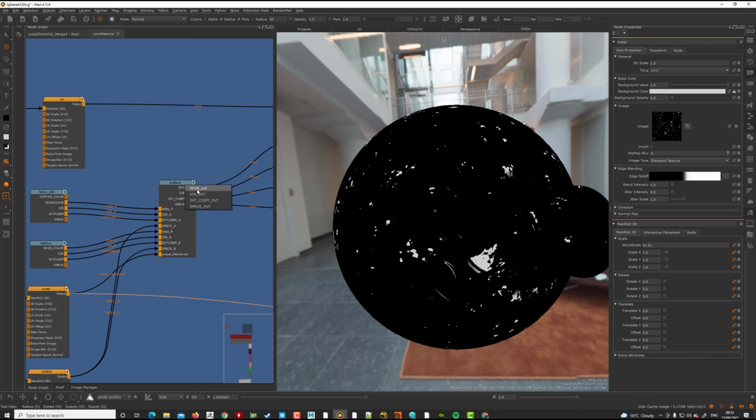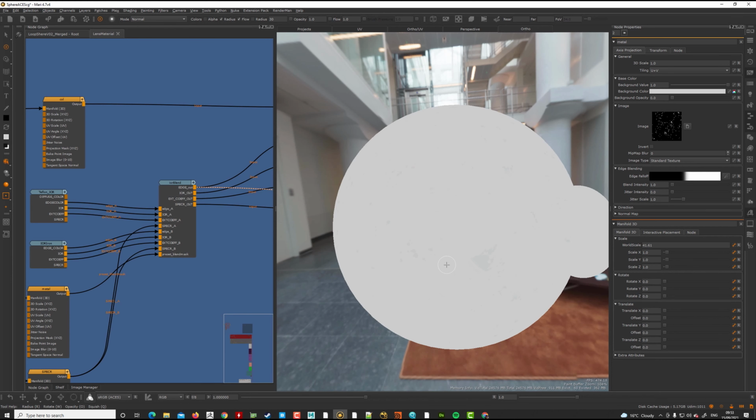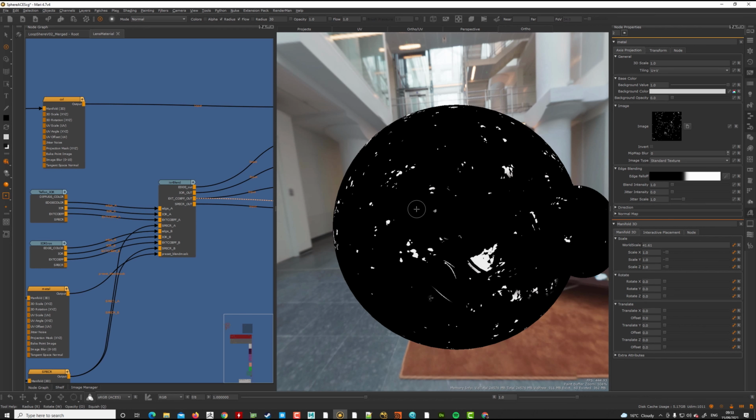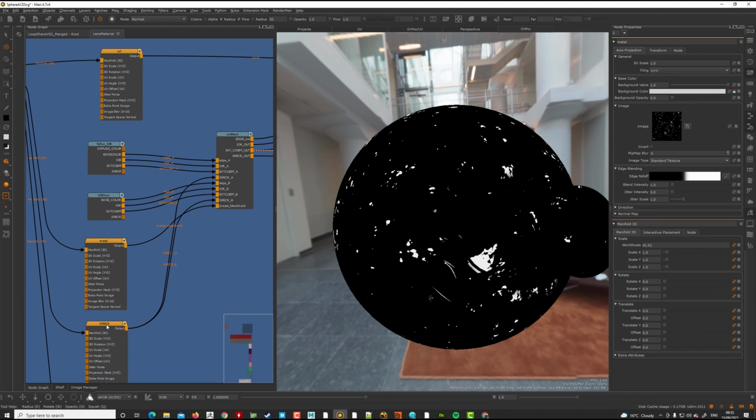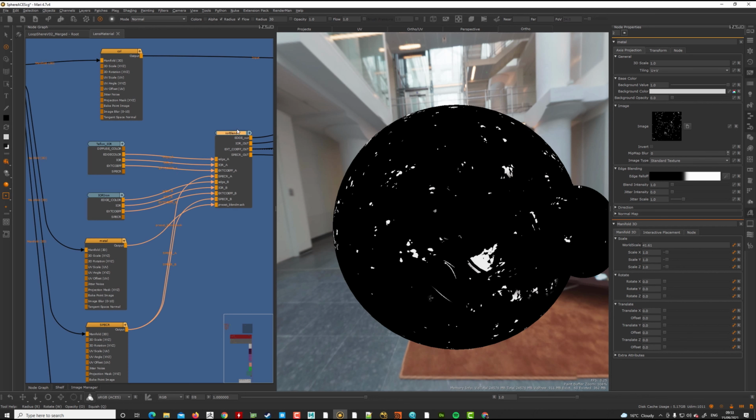Let's take a look at the maps here. Edge color out is going to be looking kind of whitish. IR is going to be the index of refraction values for these two materials, so these are float values. Some of the values here are far beyond one. Extinction coefficient is where, for example, it's non-metallic, it's going to be black, and you can see this is also float values. I'm also blending specular roughness between the two materials using this blend node that I created.